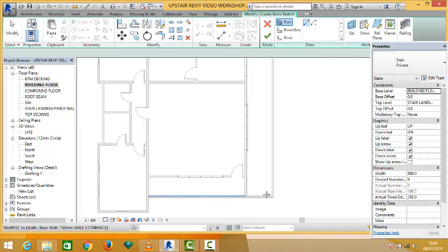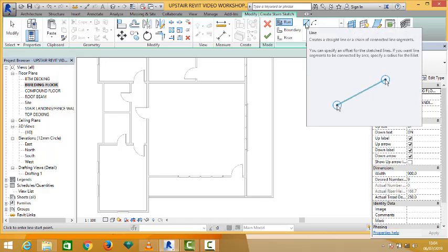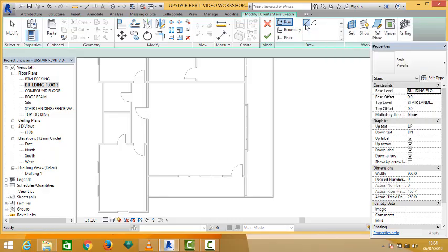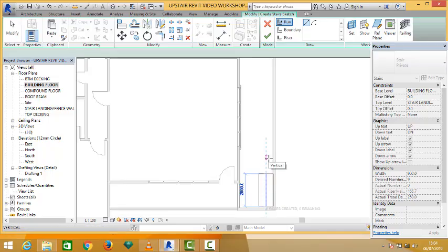250 is okay. So very quickly, if this line 2 were not checked, you will check it. You pick on the line 2 so that your stair will be aligned on a straight line. So I picked here as my start point. Okay, I begin to draw my stair.